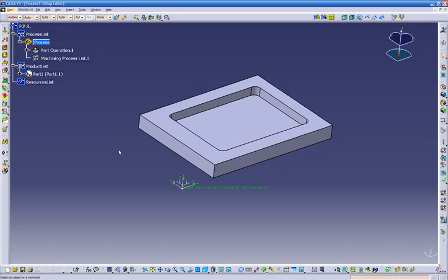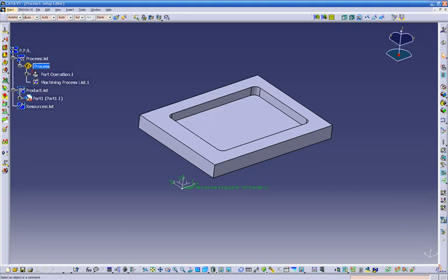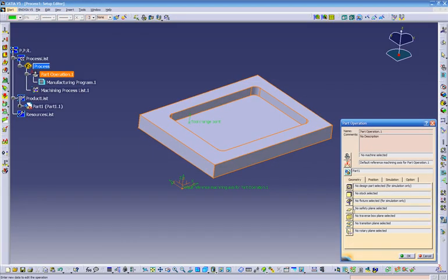What I'm gonna show you first, before we go any further, is a tool library that I already have, so we don't have to create our own tool library, and I'll show you in a minute what I'm talking about. Every time we start advanced machining, the very first thing we have to do is set it up. First, we double click on part operation, and we get our part operation window. Every time we have to get familiar and used to that. We always have to do this.